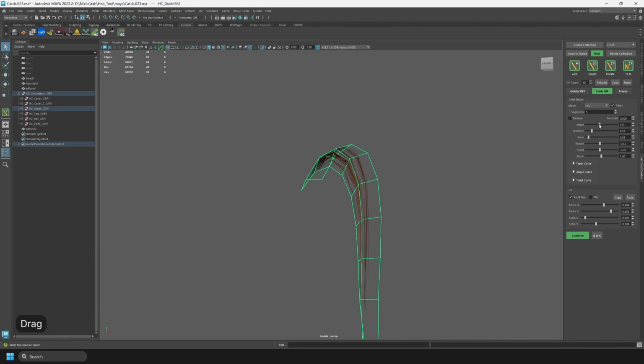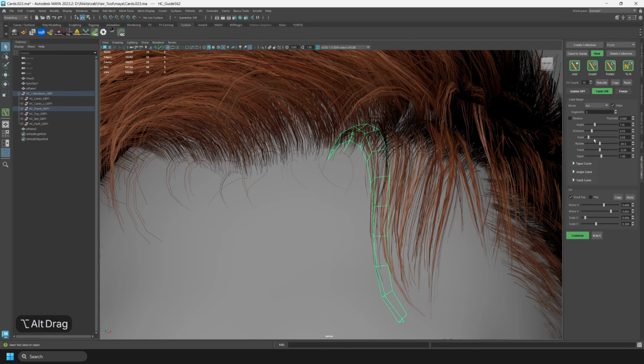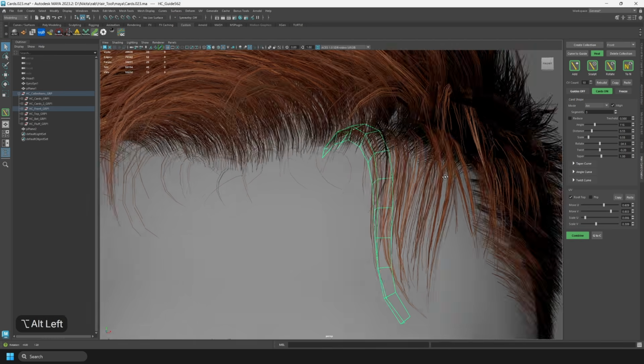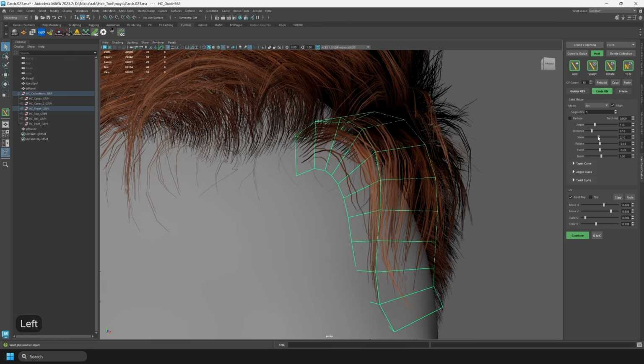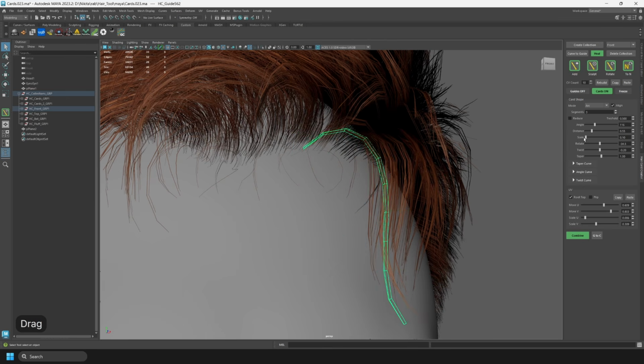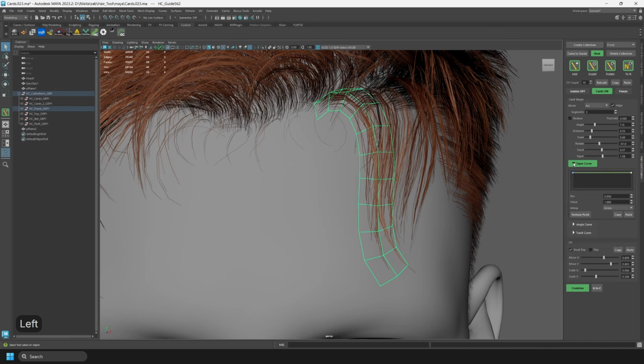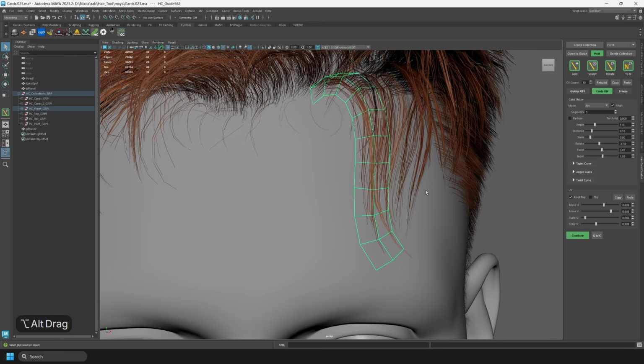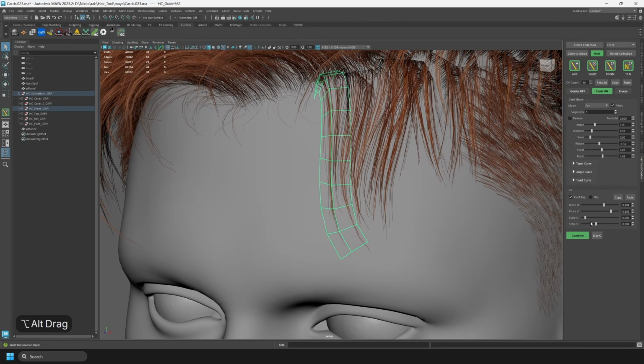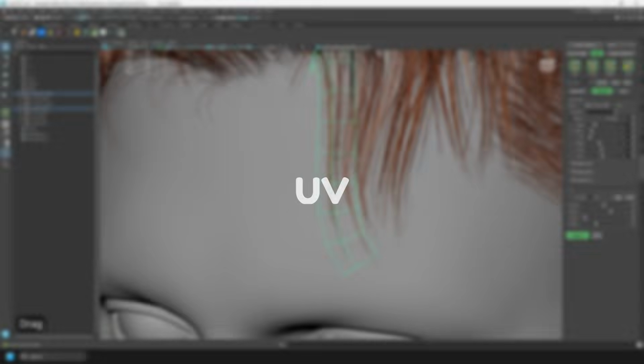Angle controls how convex the card profile is. Scale controls the overall size of the cross-section, which effectively means the card width. Rotate rotates the card around the guide. Twist twists the card along its length. Taper changes the width toward the end of the card, for example to narrow or widen the tip. In addition to the basic numeric parameters, there are also curves: angle curve, twist curve, and taper curve. They let you change values locally along the card, instead of using only one global value.